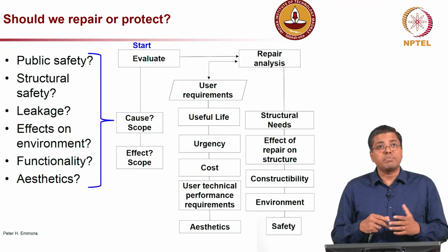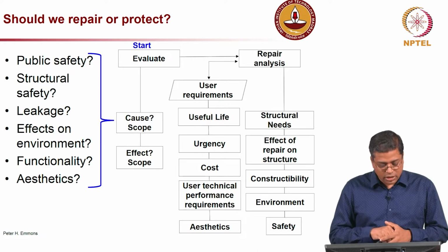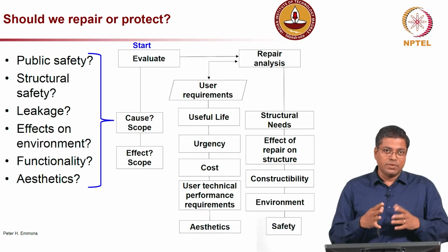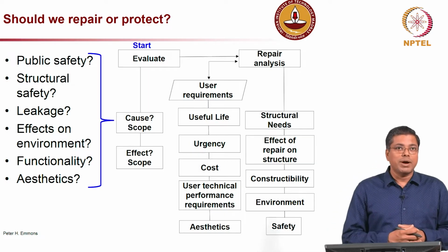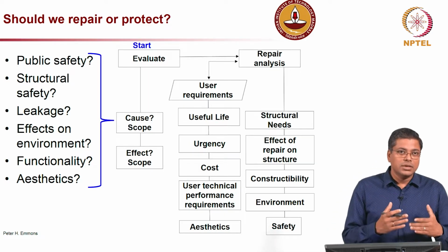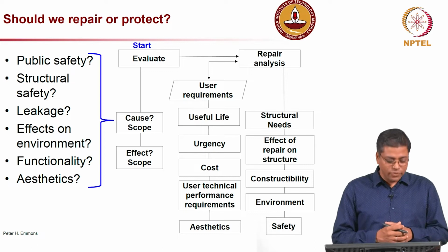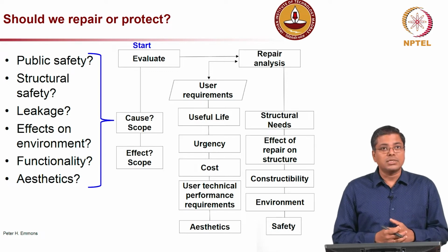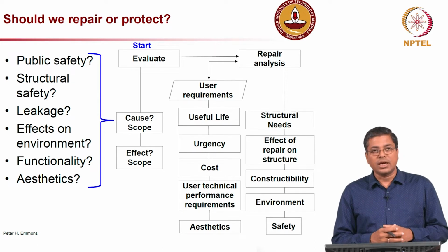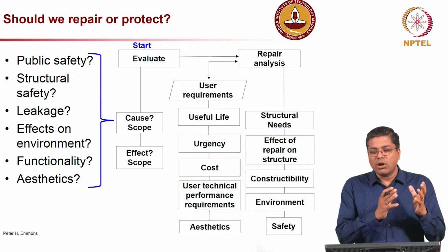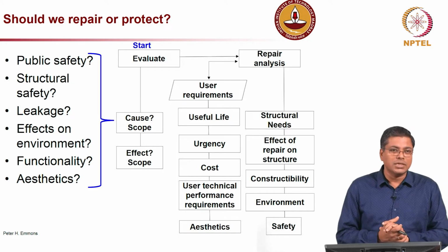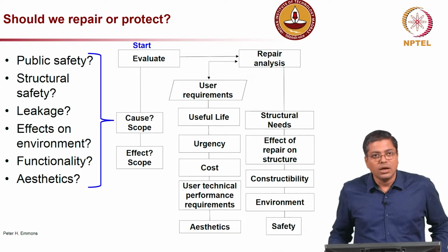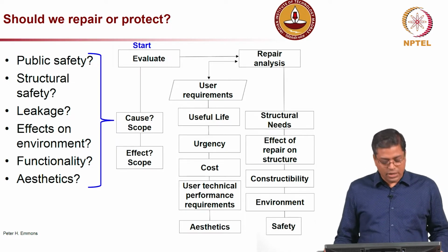Now, should we repair or protect? This is a big question because money is involved. So, how do we decide? You have to first look at public safety, then the safety of the structure itself, and then leakage, whether there is significant leakage. If a small leakage is leading to a large problem, then we can just arrest the leakage, and that will prevent further damage to the structure.